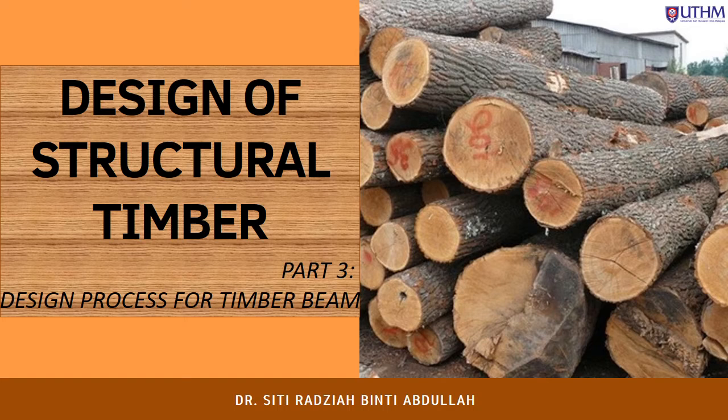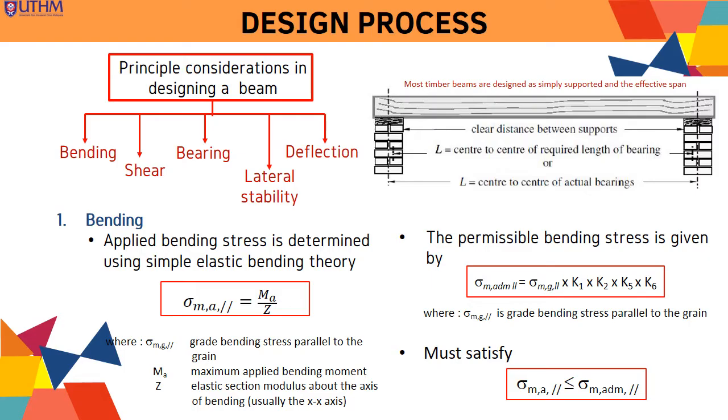Let's continue with part 3, design process for timber beam. There are 5 principal considerations in designing a beam. First, bending. Second, shear. Third, bearing. Fourth, lateral stability. And fifth, deflection.